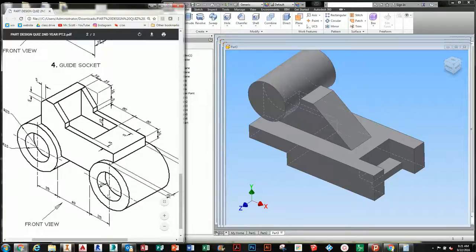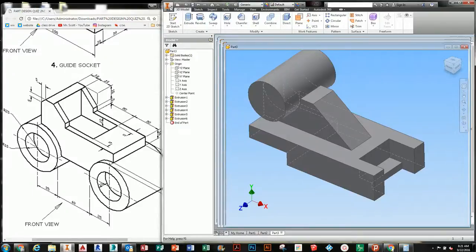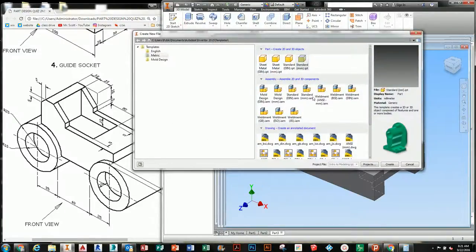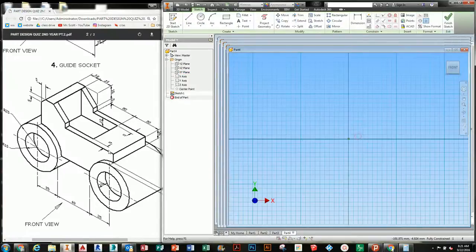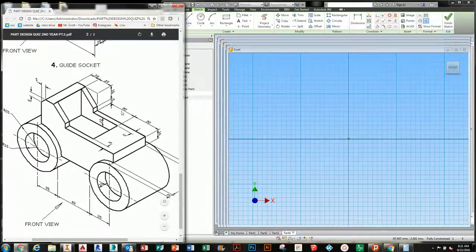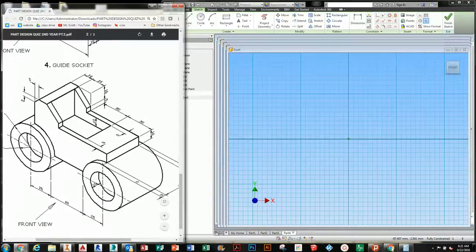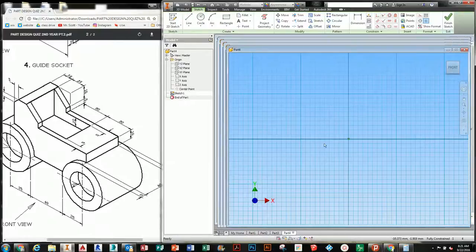We're going to start with the blocks here, this major center block, and then we're going to add the wheels, and then we'll cut out this part for the seat. So I'm going to make a new part. And we're going to sketch on the XY, and I'm just going to make this box first. So this box is 30 by 30, that's 60 plus 15, 75, 85 long, total distance 85 long by 40. So it's 85 by 40.